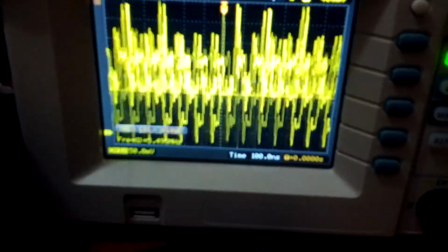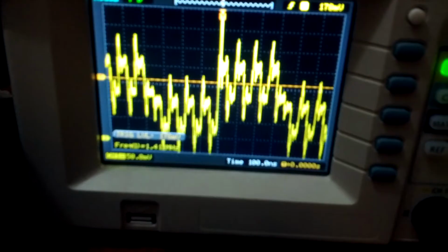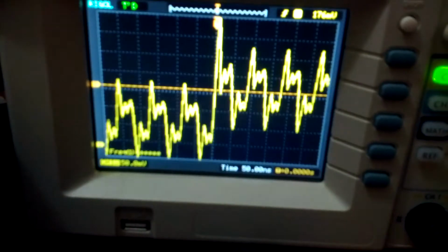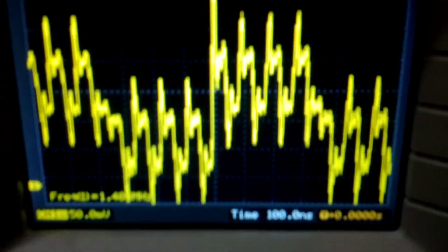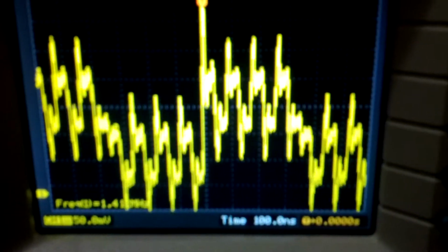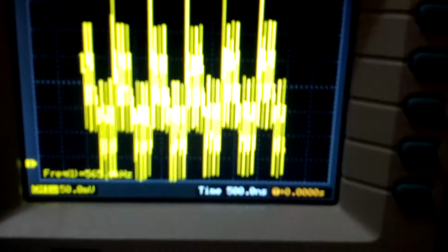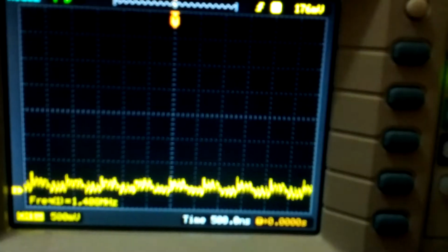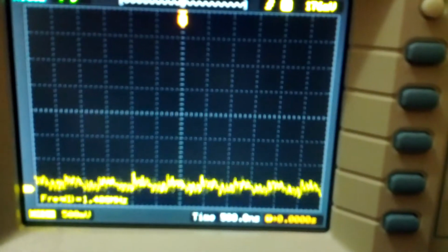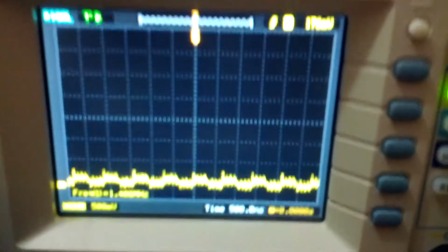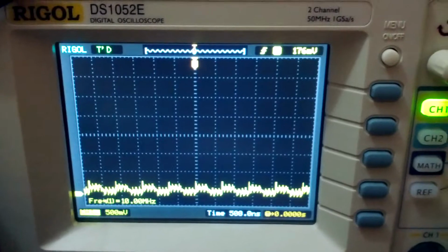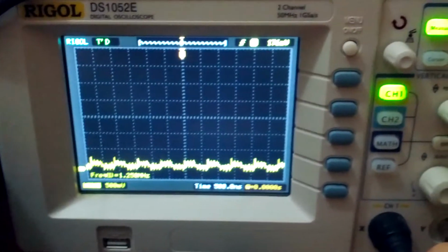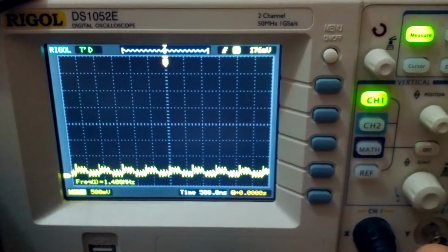If we zoom in and increase that, ta-da, we have a 1.41 circa megahertz signal, but it is not working at all. I mean, it looks more like noise to me. I have to understand why this happens. This happens anyway for every other sketch that I tried to run on the Teensy, even if it is not containing any HiFi Audio CODEC Module code whatsoever.